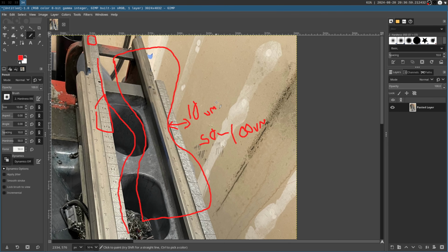Basically, it cuts out some random wishy-washy, only selective areas are in tolerance. Only worrying about the things that actually bear is the correct way to do parts, right? You shouldn't spend time improving something that literally is not relevant to the precision of the machine. It's just literally a waste of time.